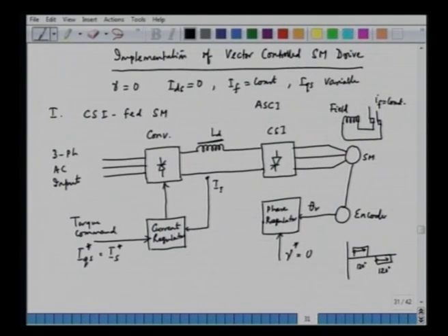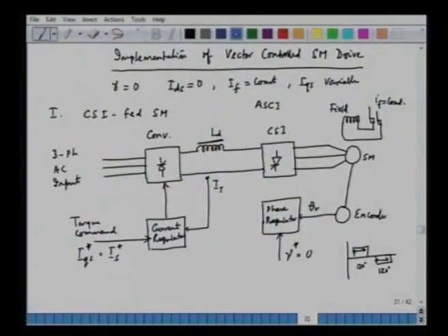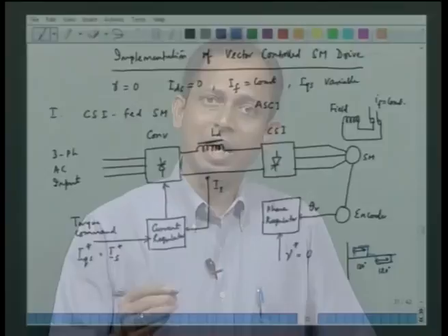However, when the current increases, there is a progressive delay in the overlap. We call that an overlap delay, and because of that the current actually lags by some angle. The actual current takes some time to rise and some time to fall, and similarly in the opposite direction. So, effectively the current is delayed.